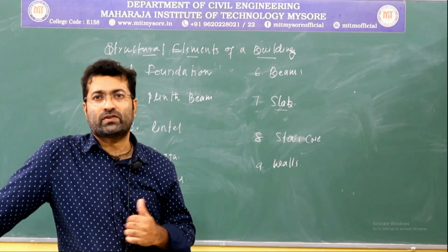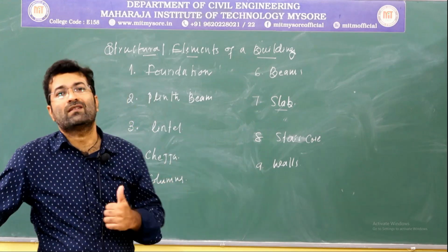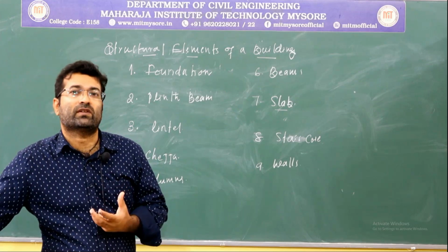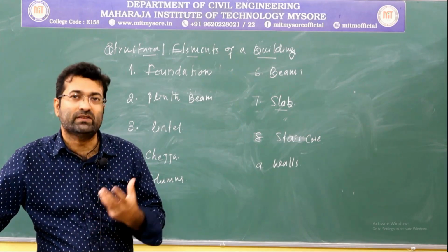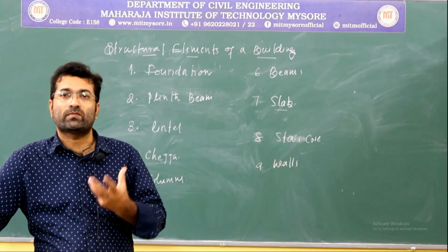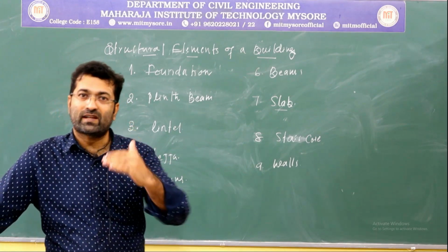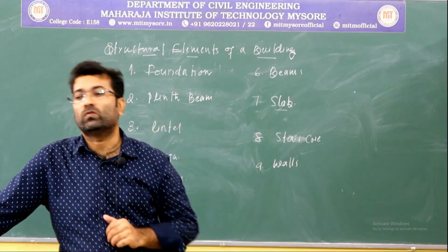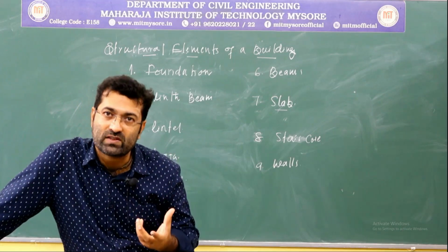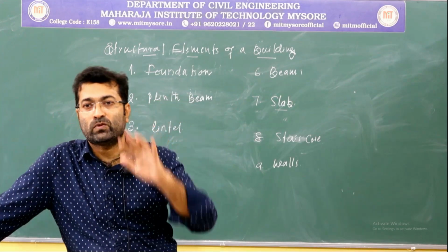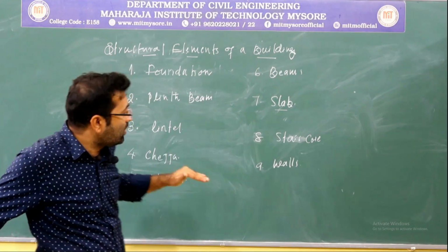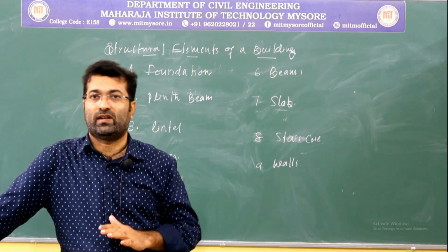So in the framed structure, we don't treat walls as a structural component, but there are some construction activities, some buildings where we don't go for the framed structure, that is, we don't provide the columns and beams. The slab is cast directly over the walls. So in such circumstances, the walls will be transferring the load of the slab to the foundation. So under those situations, the walls will be treated as structural elements.